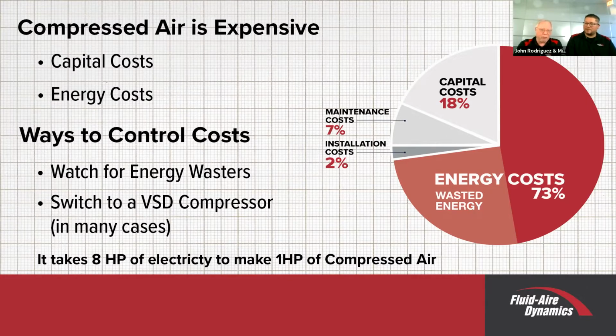There are other ways of saving energy, however. The type of compressor I just mentioned earlier. If you have a fixed speed machine, for example a modulation air compressor, which is one that stays at a given pressure while the flow through the machine changes, you can be at 50% load and still be using 85 to 87% of your energy. And even in a load-unload compressor, at the unload point, it's using somewhere near 30% of its energy. So as you save wasted energy or compressed air usage, you will find that the compressor you have makes a big difference on how much energy you'll save.